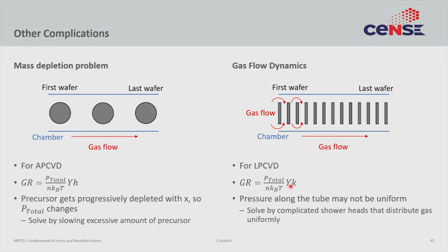Now, we ignored this effect by me saying that in gases typically the pressures are uniform, but if you stack these wafers very close to each other, then it is possible that you create a non-uniformity in the partial pressure as you go from left to right, because the only way this area is getting fresh precursors and this area is getting rid of all its byproducts is by diffusion, right, because there is no active flow between the wafers.